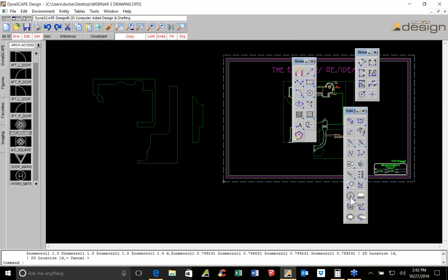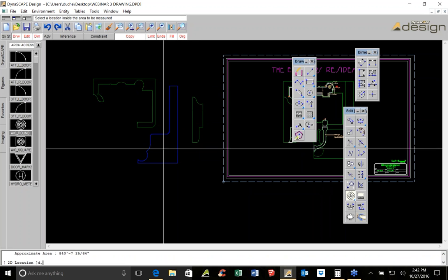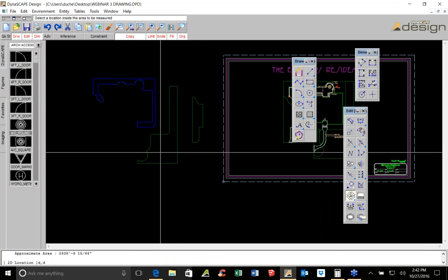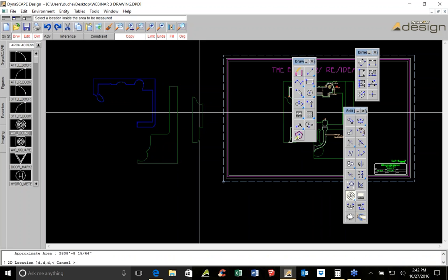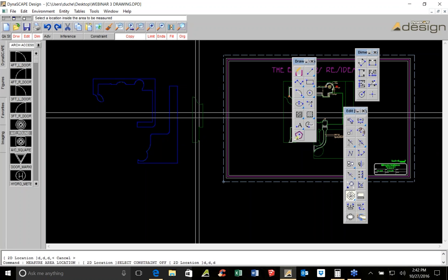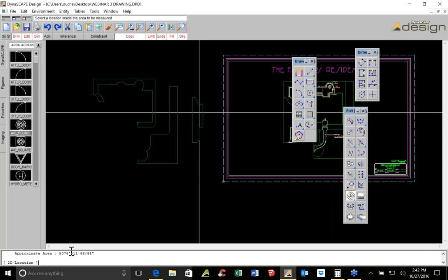The clumsy way is to go left, right, and add that. Left, right, add that. Instead, just click 1, 2, 3. So when I say click 1, 2, 3, I'm left click, left click, left click, right click. So very quickly, I can measure my lawn.